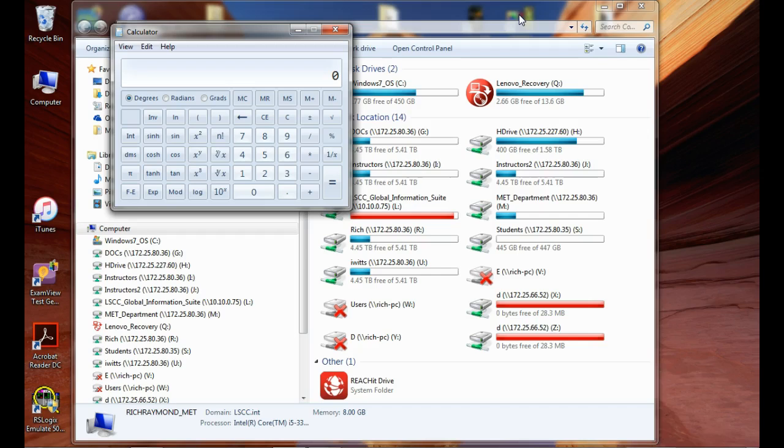That's going to wipe out that 5 volt supply, because now my regulator has to drop all that voltage at that current. So what we're trying to do is get one as low as we possibly can and still have enough to regulate at the current that we want. So if I want a 12 volt supply, would a 12.6 transformer work?